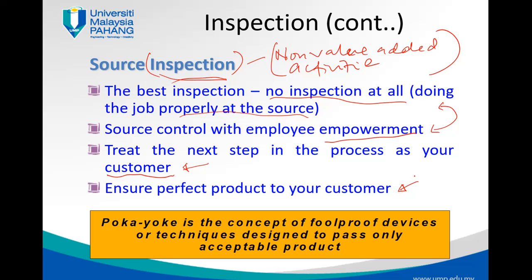Okay. Then Pokayoke is the concept of a foolproof device or technique designed to pass only acceptable product. So Pokayoke is basically a concept where we want to make sure that the process or the assembly is done in the right way for the first time.